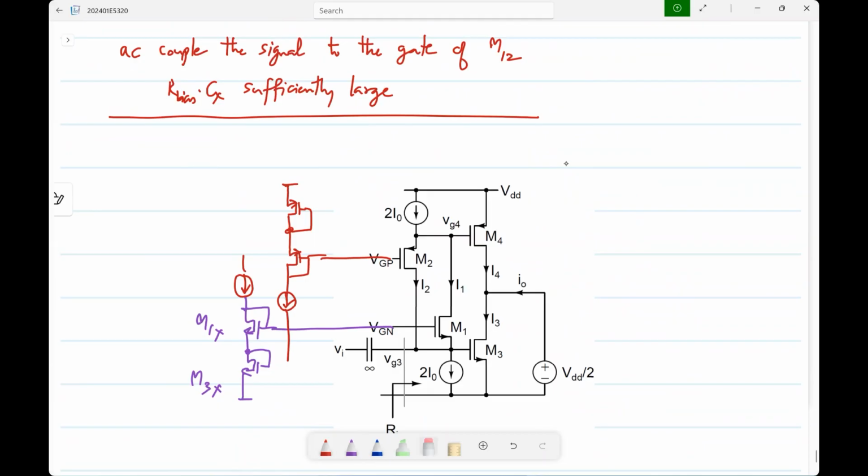Okay. Well, I'll describe it a little more, but basically the idea is you get infinite resistance here like a common source amplifier. You have the same signal swing here and there so that both the currents are dependent on the signal. Both the upper and lower currents are dependent on the signal. And you have well controlled bias currents through the devices. Okay. You can think about them. I'll continue from that later. Any questions? This is called class AB biasing.